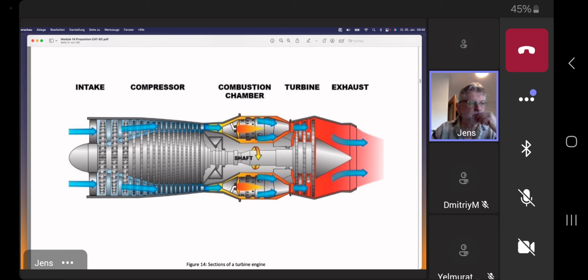Also, coming back to compressors, because the compressor is very sensitive regarding stall, they had to do a lot of things to avoid stall. We have to make sure that the air is always in movement through the engine. It is not allowed to get stuck, or that the airfoils lose the connection with the air, which means stall.